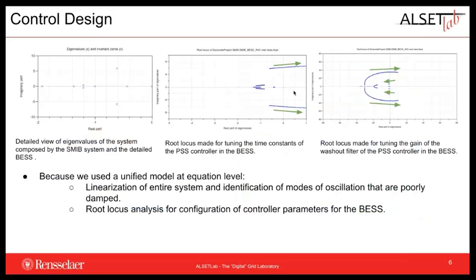And using this approach, we could linearize the entire system because it was basically built under the same equation-based platform. And we could check the eigenvalues that represented poorly damped oscillations, and we could perform root locus analysis to properly tune the battery controllers, as you can see in the center figure and the right-hand figure. We could set the parameters of the battery's controller by making root locus analysis in the entire system.